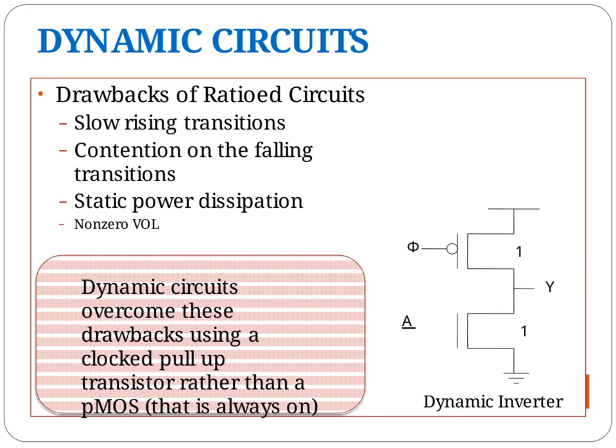The dynamic inverter shown here illustrates this concept, where the clock signal controls the pull-up device, enabling efficient operation and overcoming the limitations we see in ratioed circuits. This approach is crucial in designing faster and more power-efficient digital logic.